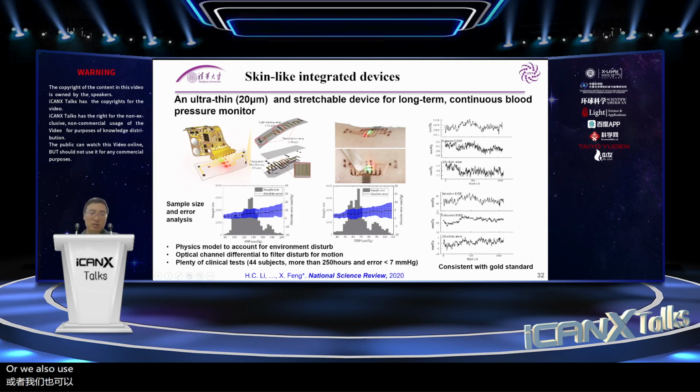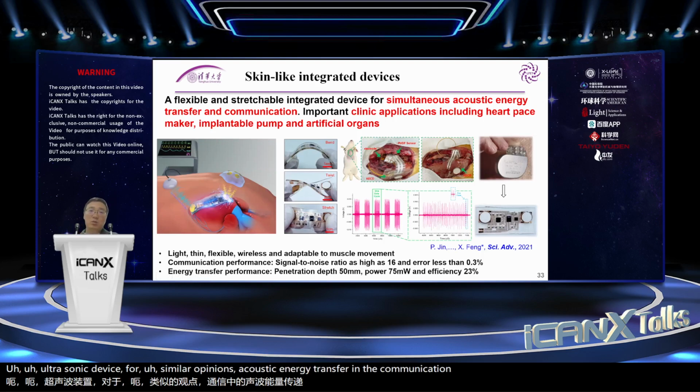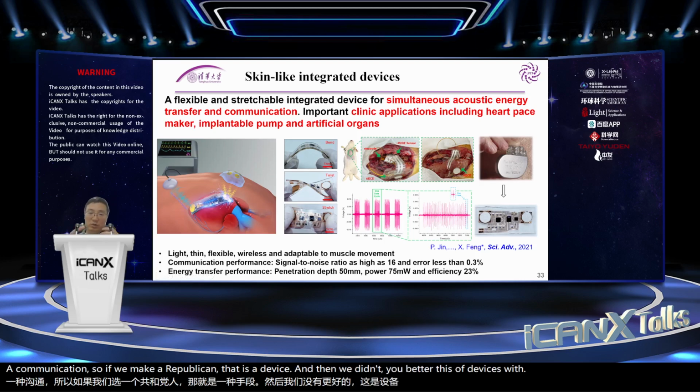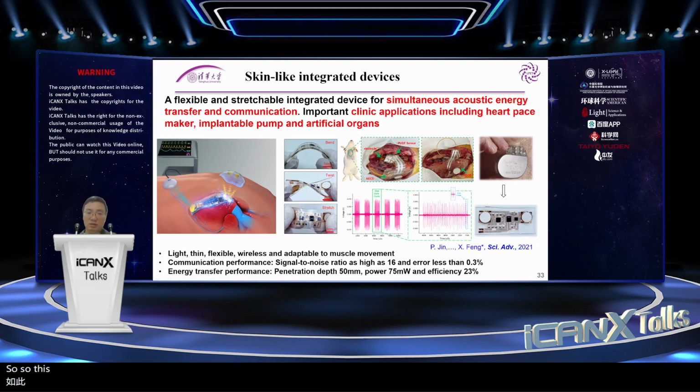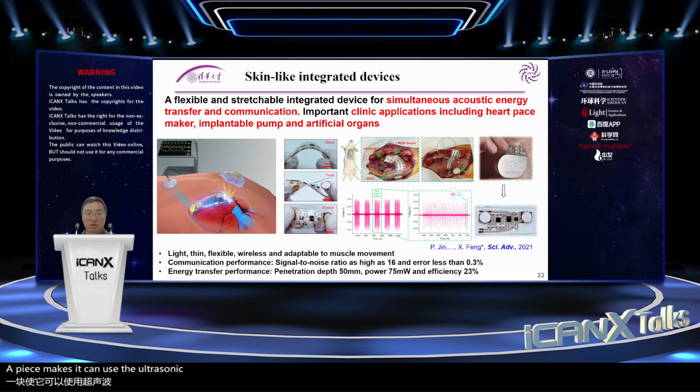We also use this approach to develop a flexible and stretchable ultrasonic device for simultaneous acoustic energy transfer and communication. We use the ultrasonic as energy, and we also use the ultrasonic as communication. We fabricated this device, and then we integrated it with the heart. This is just like a pacemaker, but this pacemaker has no battery. We just use the ultrasonic as the energy, and this pacemaker can use the ultrasonic for communication.